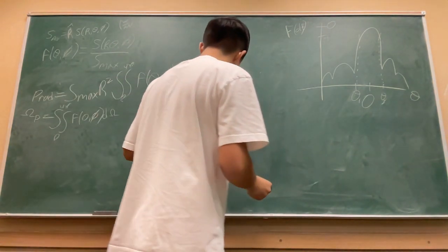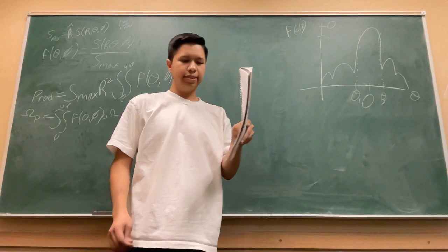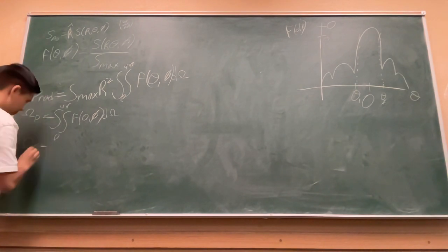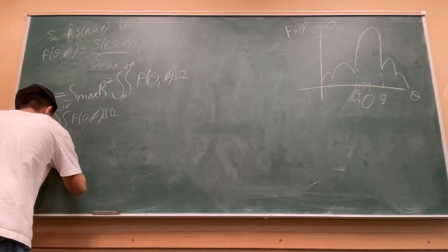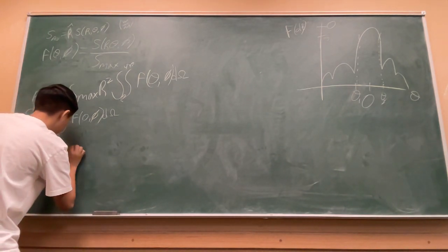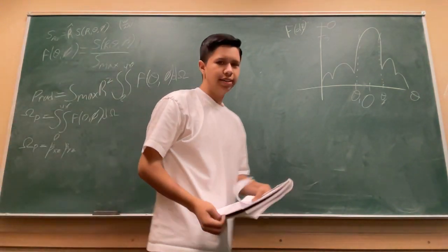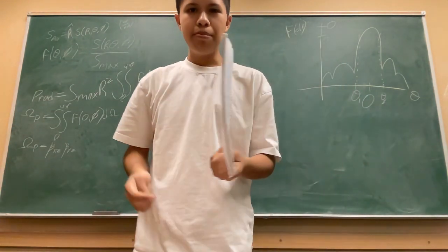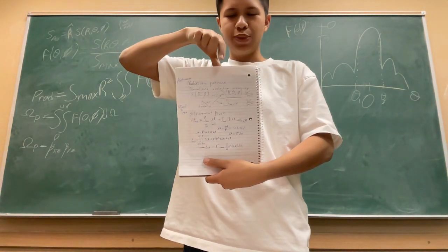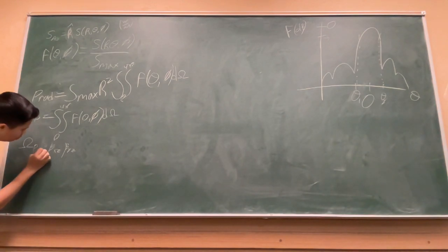And what that allows us to do is if we have 2 beam widths in 2 planes, so let's say we have the XZ plane. Let me write this down here. We're going to find the pattern solid angle is equal to the beam widths in 2 planes when they share one axis. So we're doing this in the XZ and YZ planes. If we have a beam width that's this wide in the XZ plane, and in the YZ plane we have another beam width that's this wide, this pattern solid angle we can approximate using those 2 beam widths.